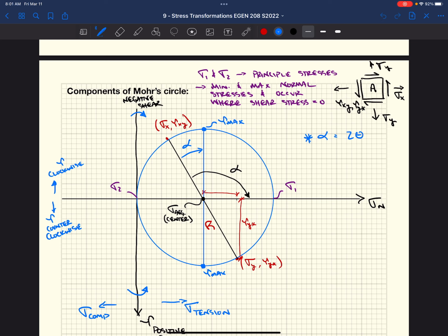Okay. We're going to continue through Mohr's circle. We'll do a bunch more examples showing you how you can relate stress states at a known orientation and figure out the maximum normal stresses and shear stresses, and what orientation we need to look at, like what angle we need to cut our material at to see those max stresses, both for shear stresses and for normal stresses. We're going to continue to jump through some of those today.